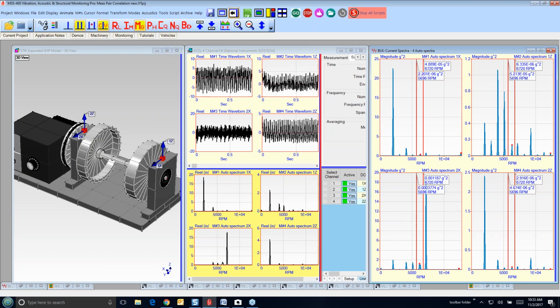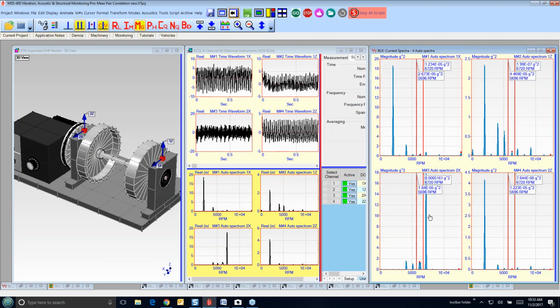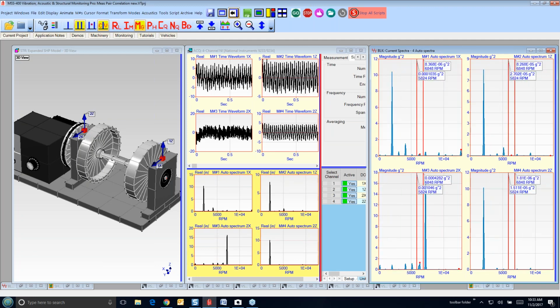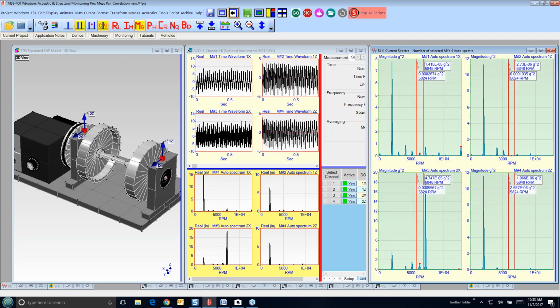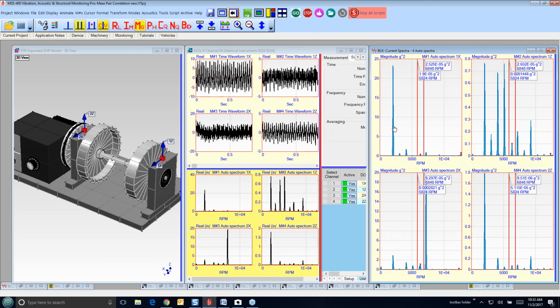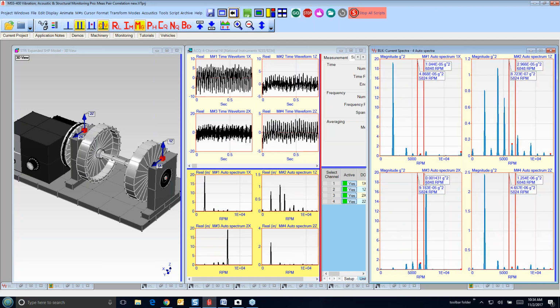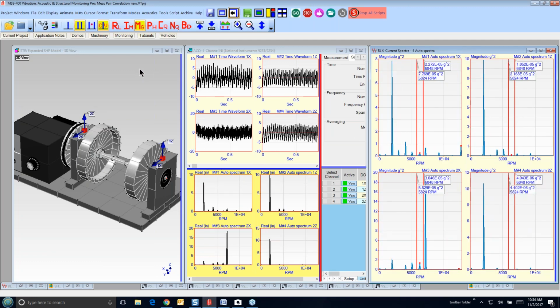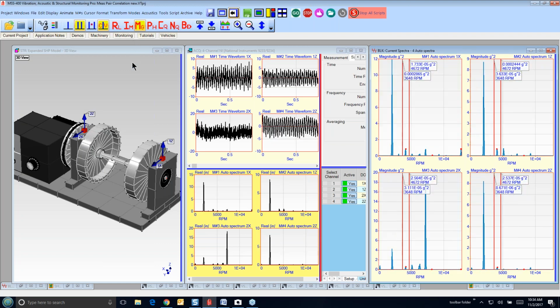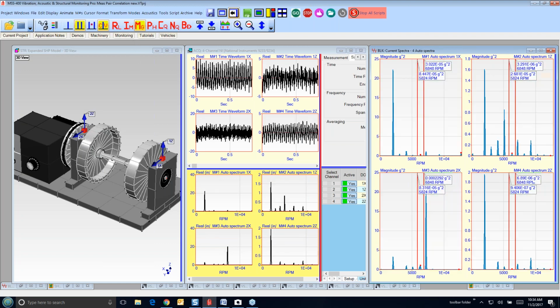And you can see I've got a huge peak here at the 4th order, it looks like. Well, we're only going to compare baseline and current for the first 3 orders. Anyway, I've got a nice strong first order peak here, baseline peak. What is the speed of that? Well, I'm using variables in these measurements.